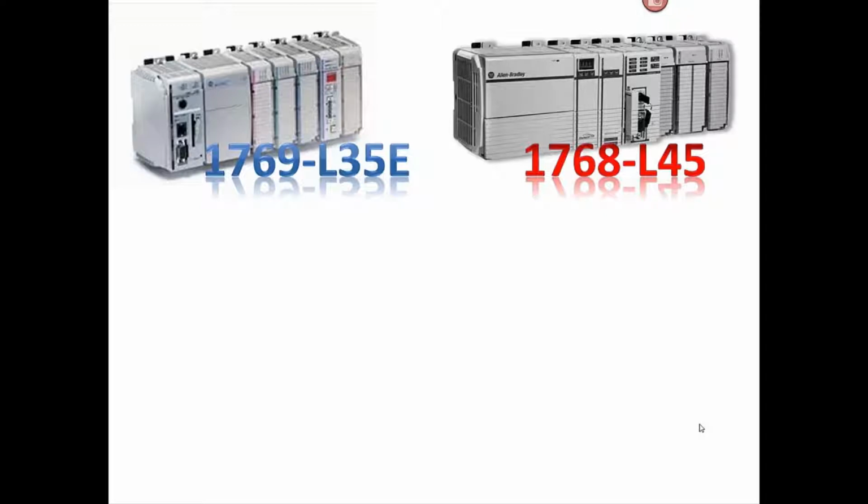And then you see the processor there has the key hanging out of it, and right below the key is an RS-232 port, and kind of blocking the view of the key and the 9-pin sub-D shell for RS-232, you have a little snap-out cover that covers up a memory card that you can slide in there. And these are standard memory cards. These aren't anything special. And then continuing to the right, you have 1769 I/O modules. You use the same I/O modules on both of these CompactLogix platforms, but the part numbers and the power supplies are completely different. So the L45 does not come with Ethernet, but the L35E does.